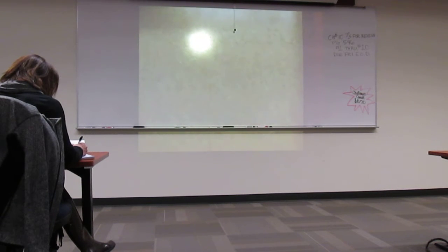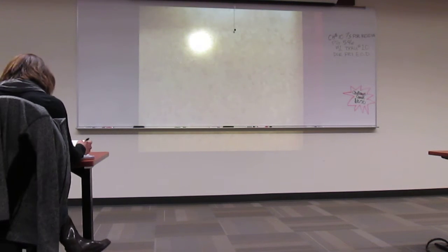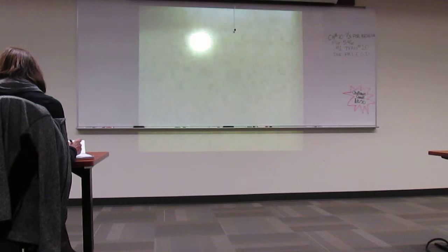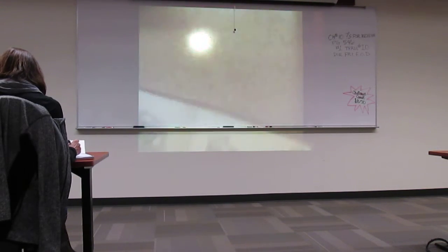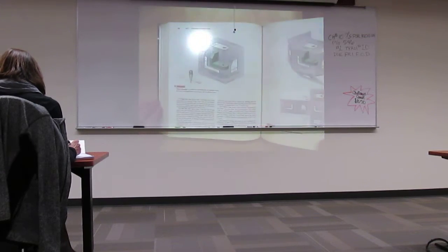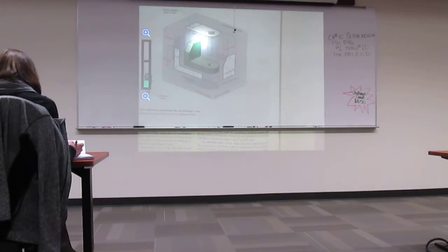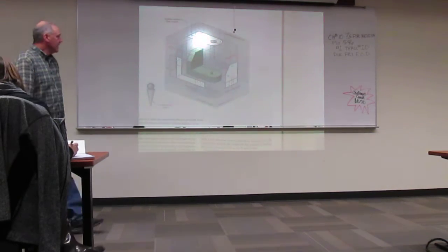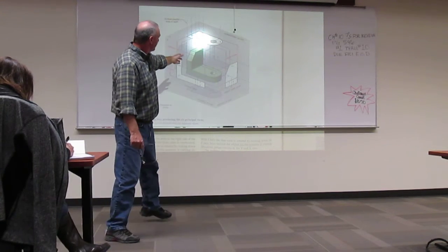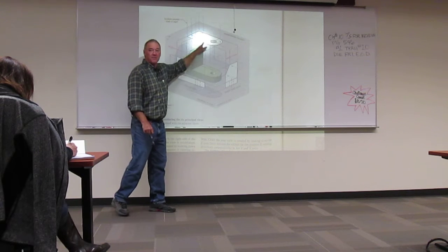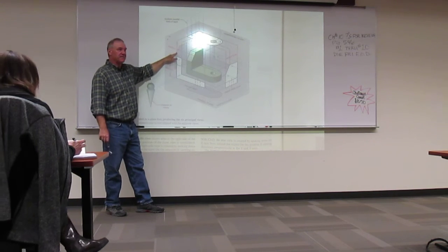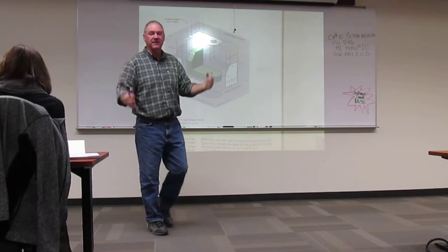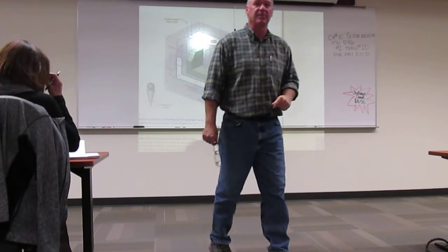Okay, after that, they go into, starting on page 493, our different planes of projection. But I'm going to skip over those figures and go right to page 499. Well, 498 would probably even be better. And we're going to talk about planes of projection. Now, when we talk about planes of projection, in essence, it's the glass box that totally sits around an object, right? That's what we do. We just take an imaginary glass cube, put it around whatever the object is. We call those our planes of projection.